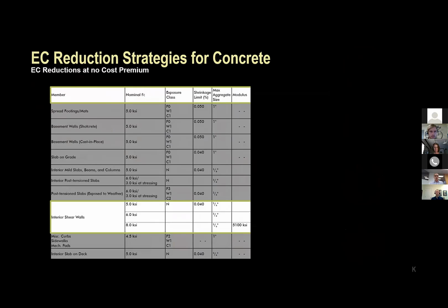So as that last image showed, if we pay attention to concrete and focus here, one of the things that is most actionable for concrete is performance-based mix procurement. Dirk mentioned that a little bit. It's really important to start working with your suppliers early on. But the more we can get away from prescriptive mix designs, only specifying what we really care about, and then letting the designers come up with the mix criteria, that is, in fact, how we can usually drive to the lowest carbon footprint solutions.